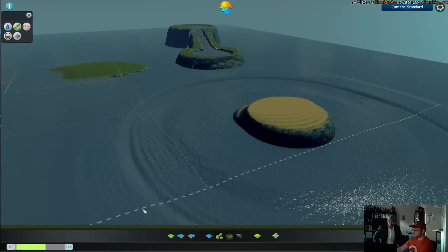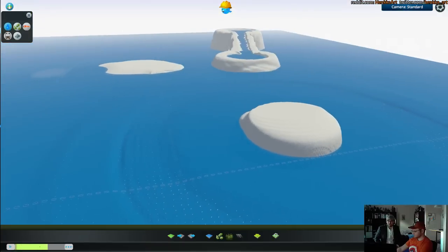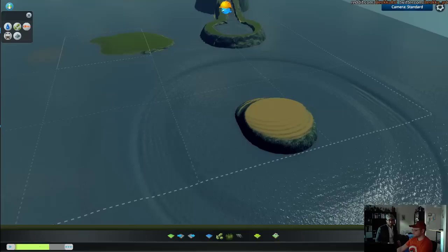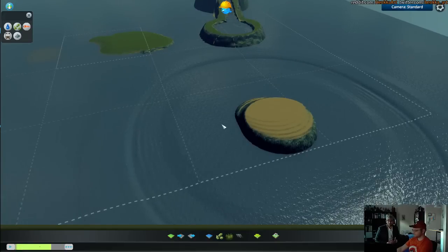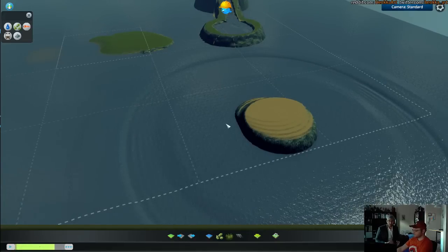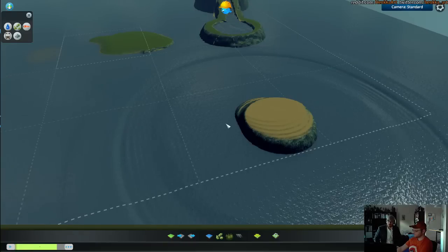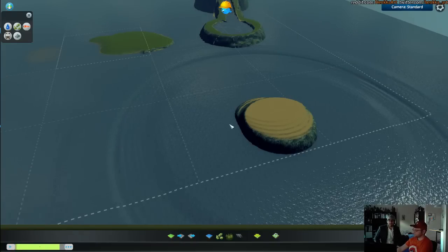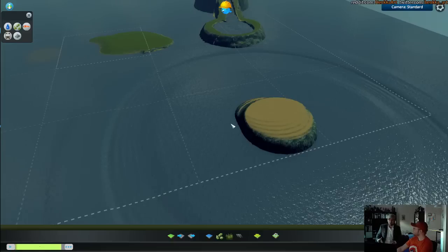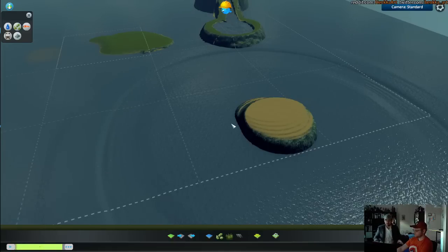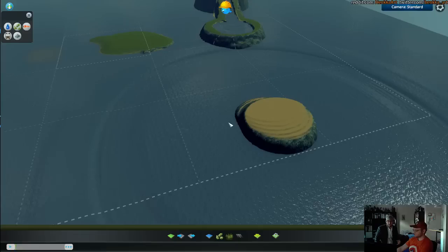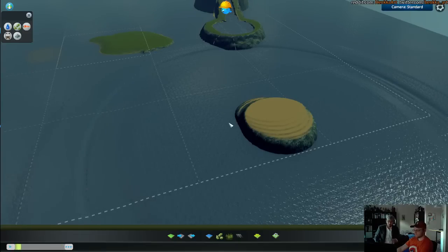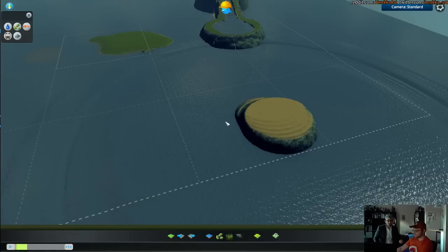And due to this, we recommend that you first work on the topology of your terrain, make it look as close to what you want it to be before starting to put water in there. Because if you already have water settled and you start editing the terrain topology, then it's going to take you a long time to get it reset into the shape you would like. So the order of things would be to start creating the mountains, the flat areas, and design the areas which will be best for your gameplay. So where do you want the players to build their city and all these kinds of things. And then once you have a good topology set up, you can start putting the water sources in the places you've allocated for them and iterate to test whether they flow properly and so forth.